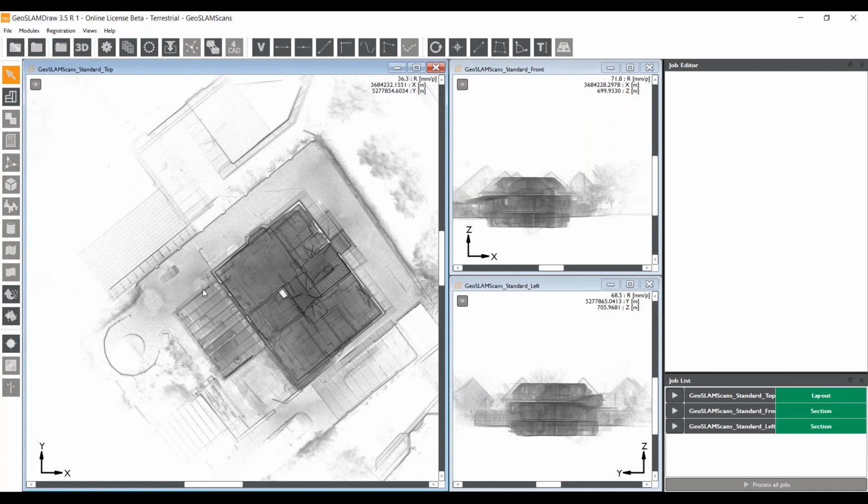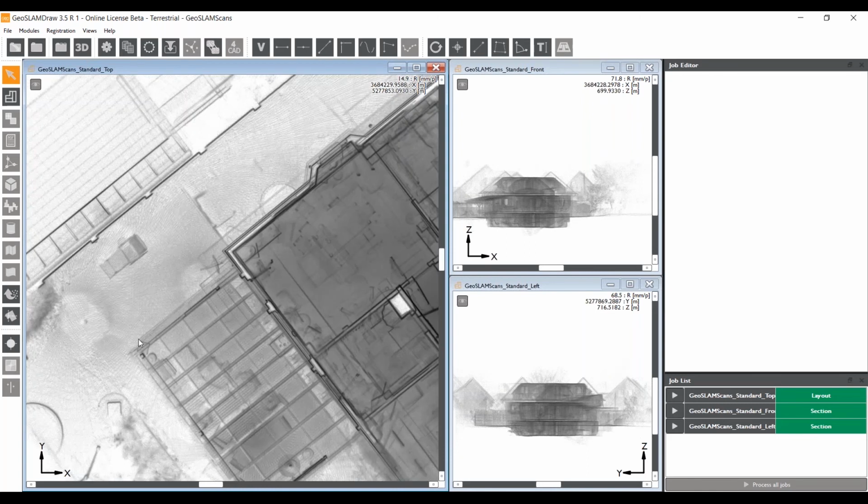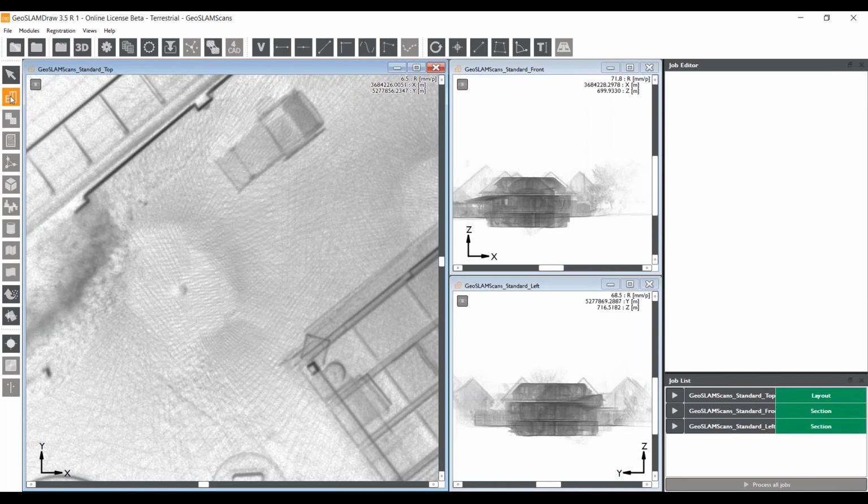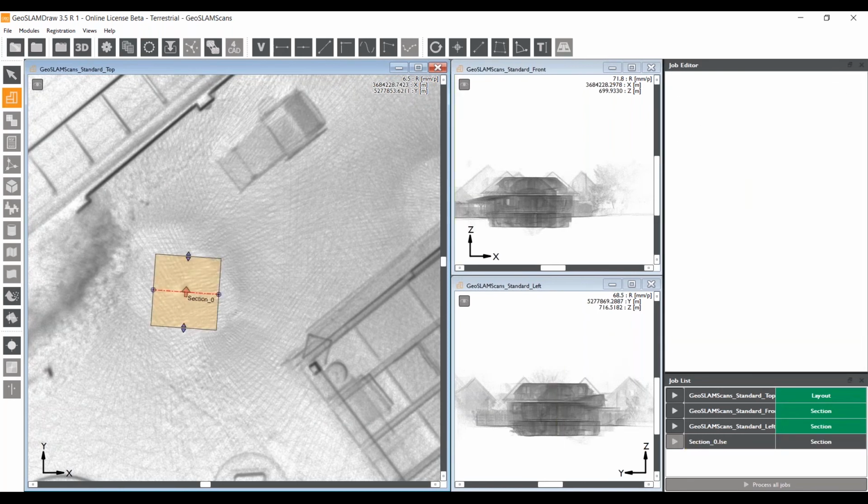So how are we going to do that, the combination? Since we used Faro scans in the outside to have a very good measurement of the facade, we used spheres in there, and we will use the spheres in Draw and in the Faro scans to combine both projects via a 6-parameter transformation. So first we need to locate the spheres. If you have made a plan in the field where the spheres are located, this is a lot easier. So for example, we can see here is a sphere.